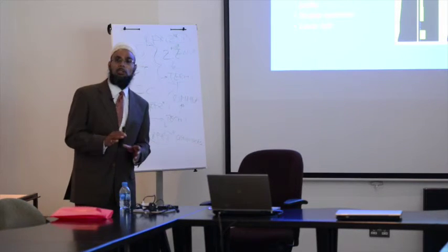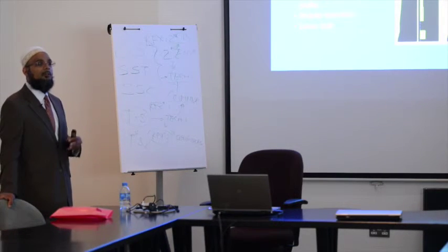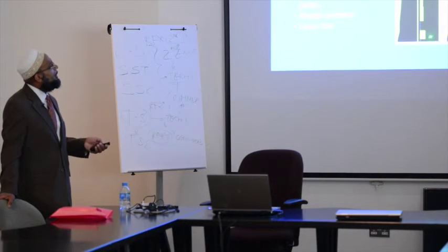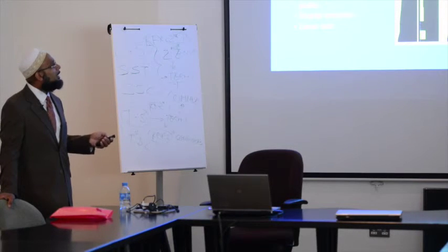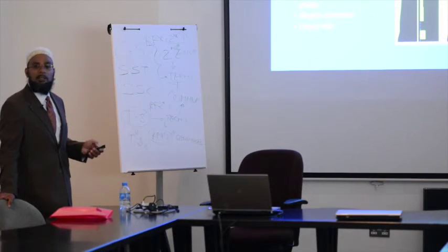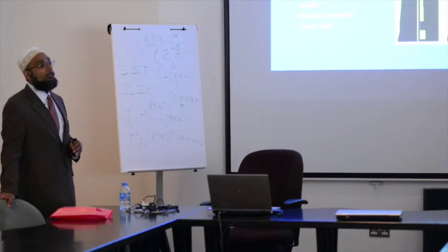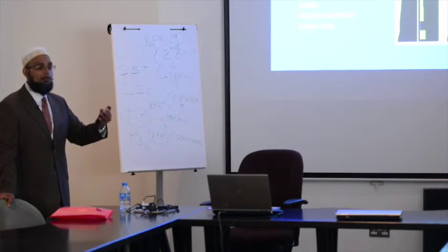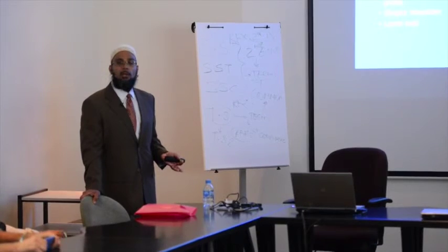So the total production was similar, but what I really admire about this company is they took the additional effort and did a flow profile. And the difference really showed up in the flow profile, which I've shown over here. Design 1 was consistently missing this zone over here, while design 2 was able to stimulate that zone. Now it turned out that design 2 was also operationally much simpler. It was offshore, so it was much lower cost. But they did not know that before going to the field trial.